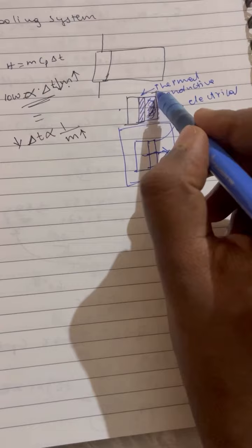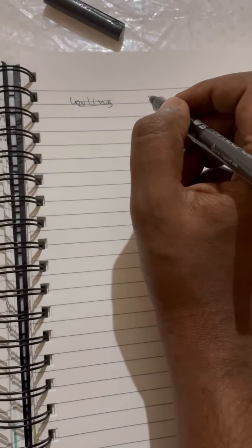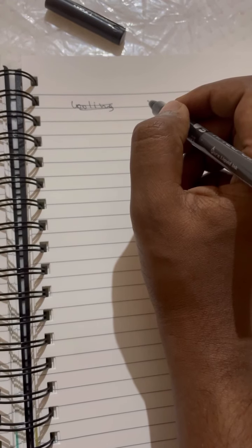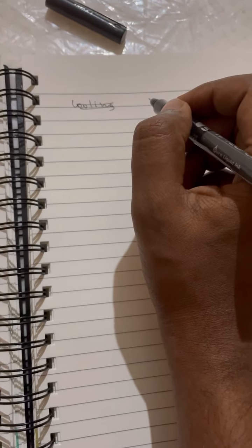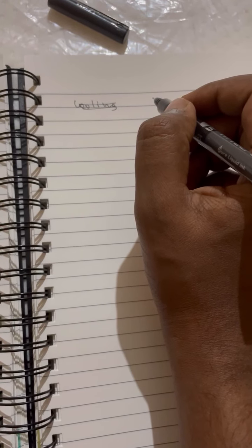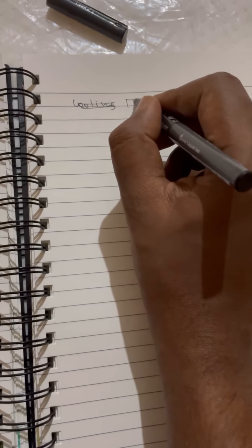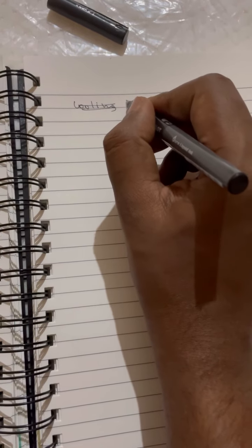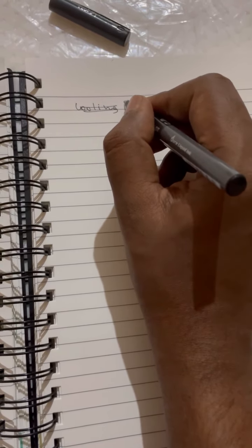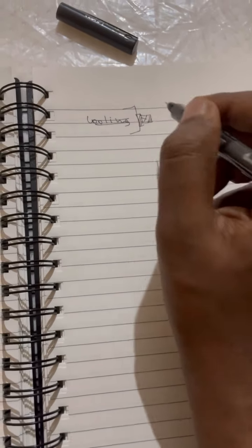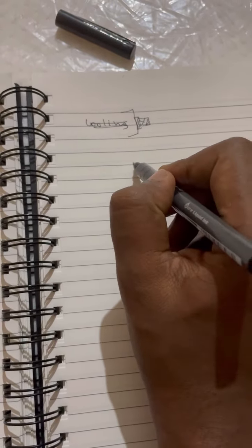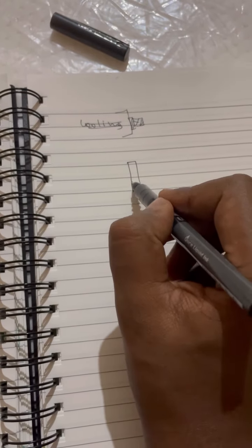And never forget to add this sheet. We have discussed electrical energy and how the electrical energy is transferred as heat energy, and how to eliminate the heat by adding a heat sink via a thermally conductive and electrically non-conductive material. So this is going to be your conductive element, this is going to be your thermal conductive sheet, and this is your chassis.